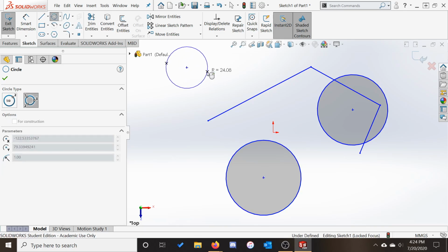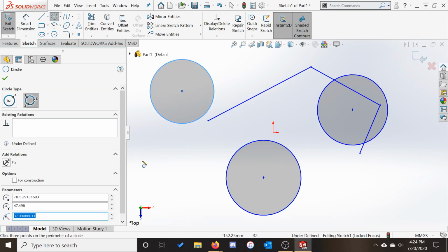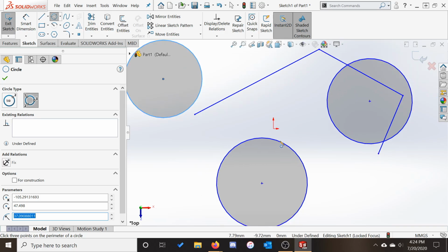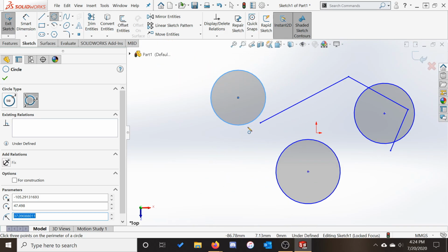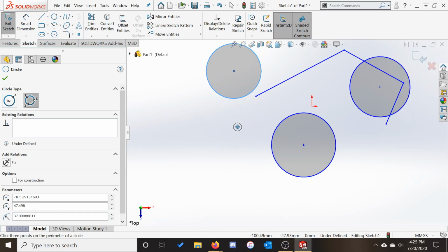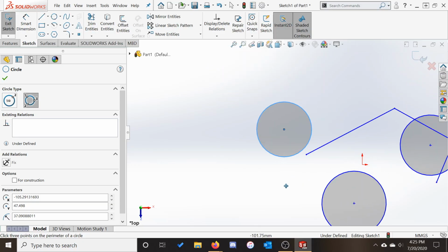As you're sketching, you may fill up the screen or find that you need to sketch in an area that you can't see. This brings us nicely to how you navigate SolidWorks' interface. We have three main tools: Zoom, Pan, and Orbit. Zoom does exactly what it sounds like it does. You can scroll on the mouse wheel to get closer to or further from the objects on the screen. Pan allows you to move which portion of the screen you're looking at. You can do this by holding down the Control key and the mouse wheel. It should make a clicking noise, and then dragging the mouse around.